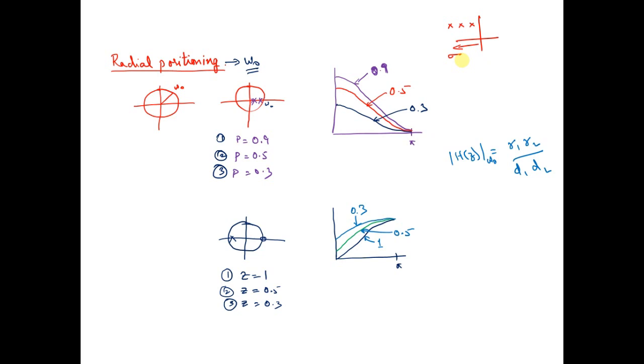The nearer to the frequency axis the pole is, the more pronounced will be the effect of the pole, and the same goes with the zeros also. The nearer the zero is to the frequency axis, the better would be its effect on the frequency. The only difference was that we could have placed the zero onto the imaginary axis. However, we cannot place the pole on the imaginary axis. It has to be slightly away from the imaginary axis on the left hand side.